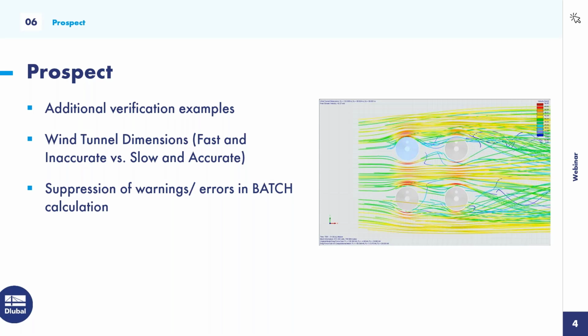It's of course highly discussed if the Eurocode is now the standard to be used, or if you can of course also use CFD analysis results. I mainly think that if you are able to compare your digital wind tunnel with real values in order to see that your model and the inputs are matching a real situation, like fine-tuning your CFD or FE model to the correct physics, I think you can use the wind loads from RWIND, because then you can assume that the results and inputs are correct. But this is always, I think, up to your standard and the person who is maybe also having a look at your file and calculations.